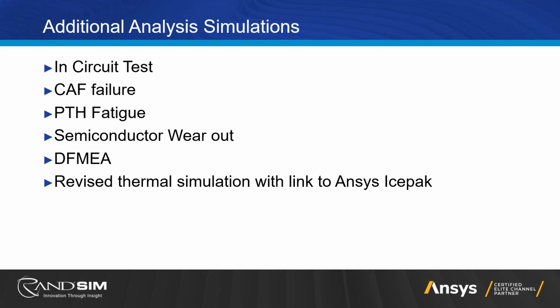I've had issues in the past where we've had failing boards, half of them would work, half of them wouldn't. We figured out that it was that flexion on the manufacturing test or the install that caused those solder joints to break. You have CAF failures, PTH fatigues, semiconductor wear out.